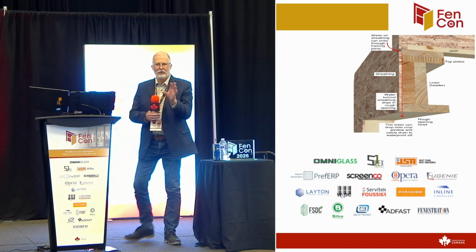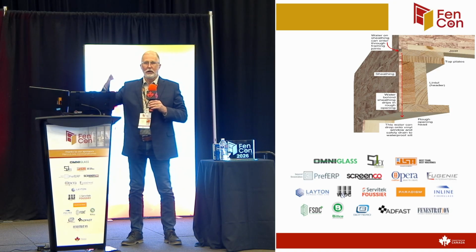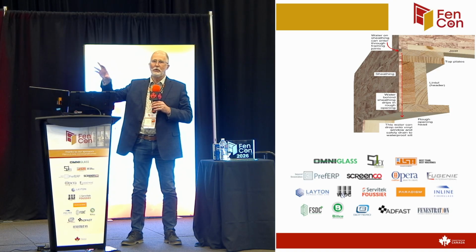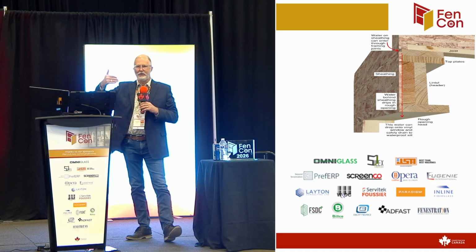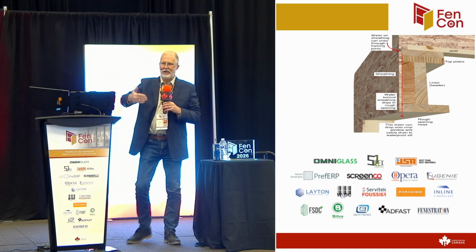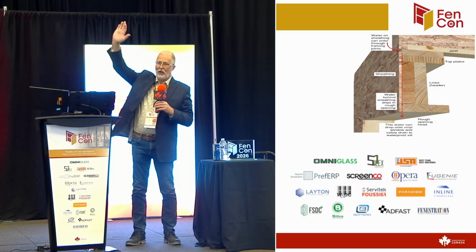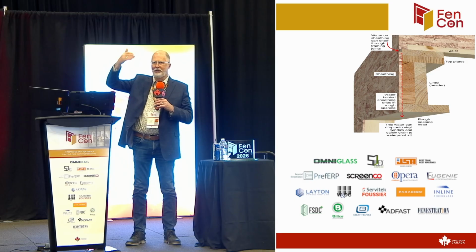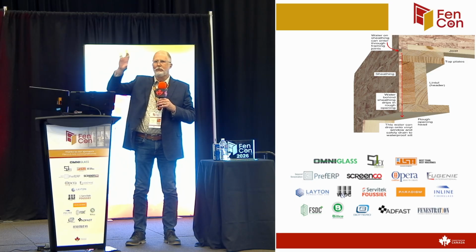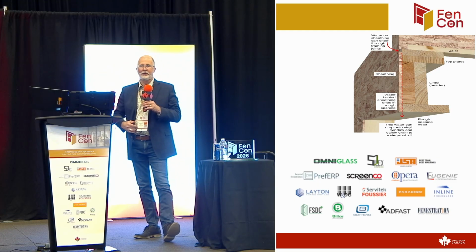It hasn't really damaged the structure in that application, right? So if you didn't get the air barrier right, you might get some frost on the inside of that frame, and what's the frame made of? It's made of plastic. So I think in terms of moisture sensitivity, and I think in terms of damage, because when I go to a building that they've sealed 4 sides and it's got $1 million worth of damage on it, I think if they'd have put sill pans in and done some reasonable sealing, there would be probably $100,000, $200,000 damage.